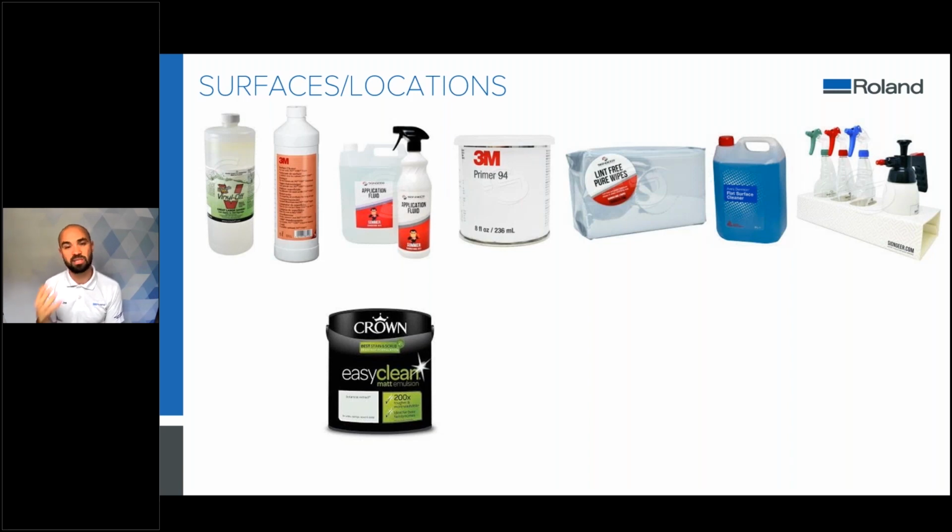However, it means that the adhesives of your vinyls and things like that may not stick as well to those paints. So if you know that a customer is going to be painting the wall before you're going to be applying graphics, just get them to check the paint that they're going to be using, and you want one that's not got one of these easy clean technologies built in, as it's more likely to push away the adhesive of your material. You can key the wall as well, like we said, with a light sand, and you can also test, which is probably the best way to go about this.